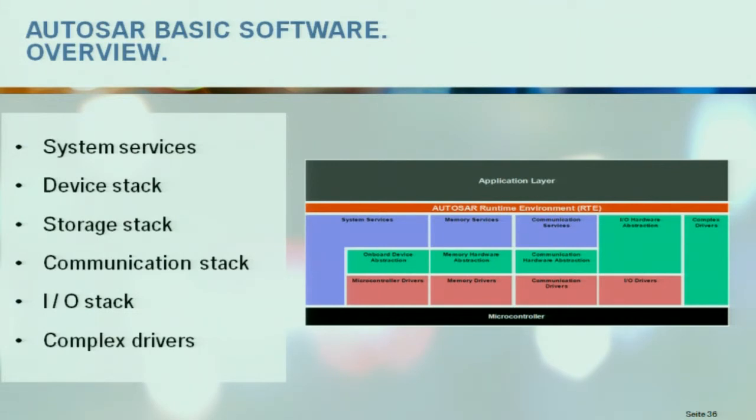And the last thing is the so-called complex device drivers, which are used to bypass all the other operating system services. If you need very fast software functionality, then you can use complex device drivers, for example, for combustion engines. They have timing requirements on a microsecond level. This is one use case.